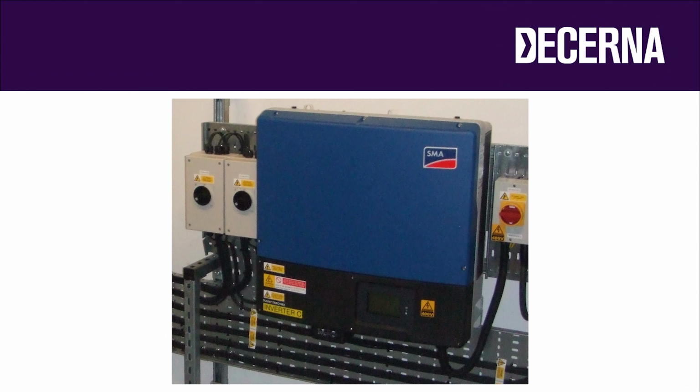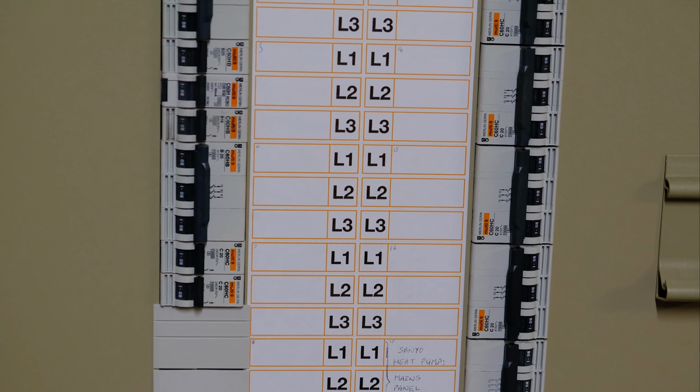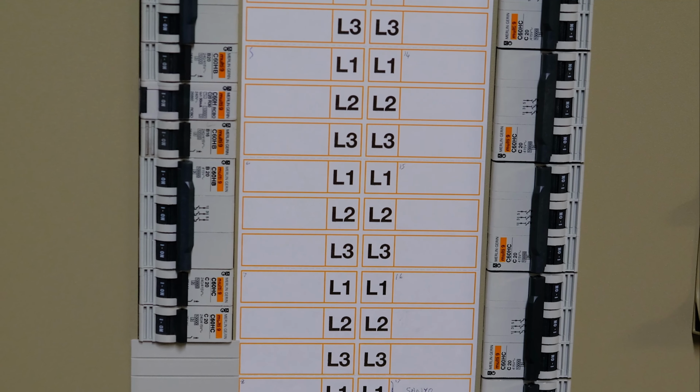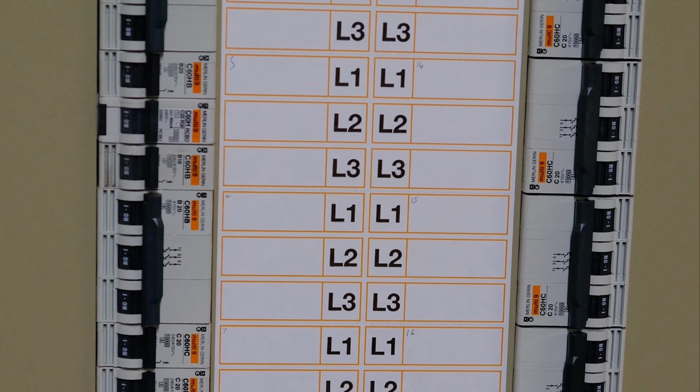The modules in the array connect together, and the DC cables run to the inverter. The output from the inverter is mains voltage AC, and this connects to your building in the same way that other circuits are connected. Most commercial premises have distribution boards, or DBs. That's where your circuit breakers are located, and the output of the inverter usually connects to the electrical supply of the building via a new circuit breaker in one of these DBs.